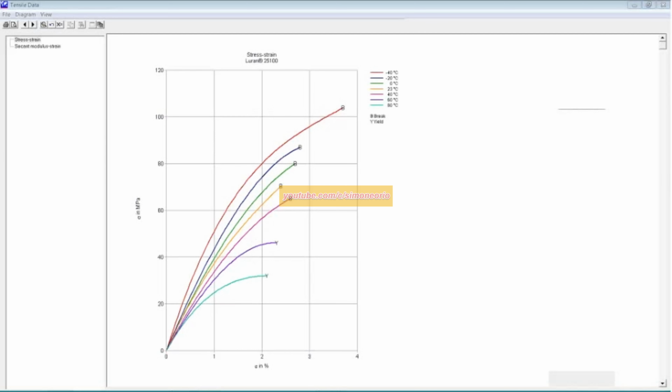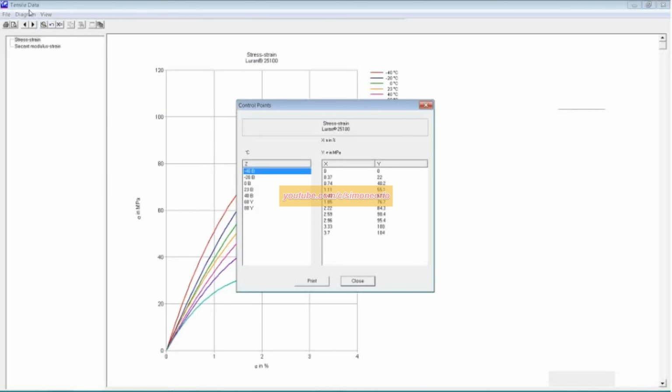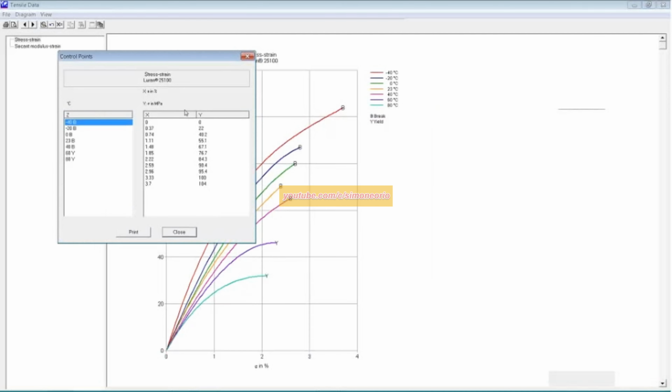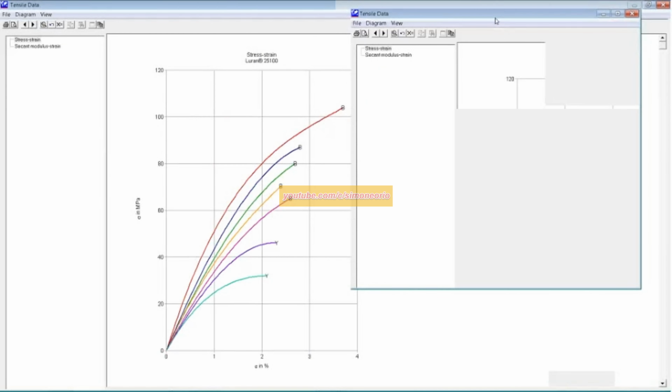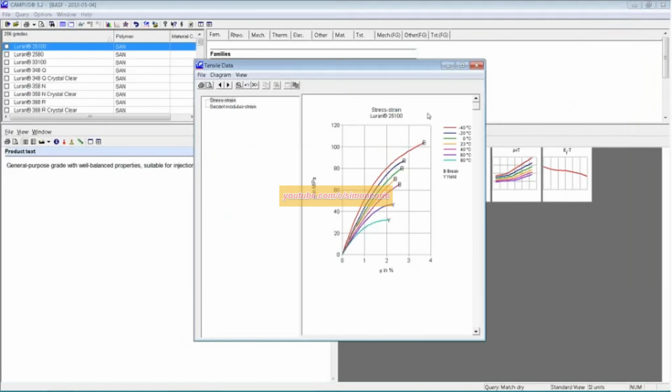So generally, when I had a real job and I was doing this stuff for real, I would choose the worst case curve for the worst case operating environment. And then we can get the XY data. Campus was nice enough to give that to us. And then we can punch this into the nonlinear curve inside SolidWorks. And then we can save it for reuse later.